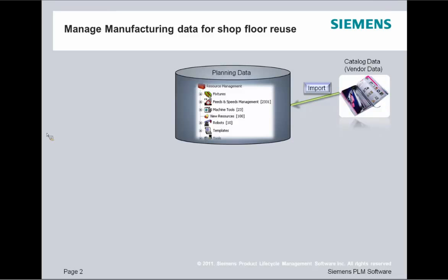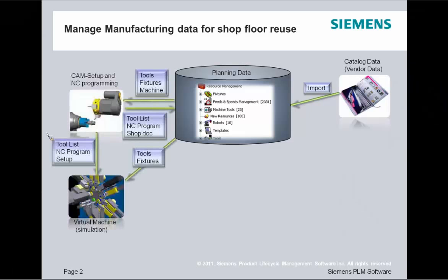That will allow you to go to a web page, pick a tool, export it in the ISO format, and then retrieve it into multiple tool libraries, such as we're presenting with MRL. Once we have retrieved those tools from the catalog and created our own, we call those our customer tools. We combine different components into a tool assembly and use those tools in different places, for instance in CAM software such as NX CAM, but also for simulation after we have created the tool path.